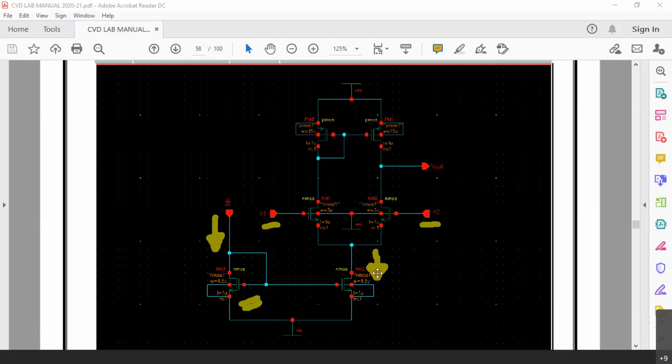So now this concept is called current mirroring. You have already studied it in the theory classes, still I am revising it. This method is called the current mirroring method. Now the advantage here is, we are using the left side NMOS as a current source, and the gates are shorted, by means of which we can control the current flowing through the right side NMOS using the left side NMOS. We decide the current that will flow through the right side NMOS also.